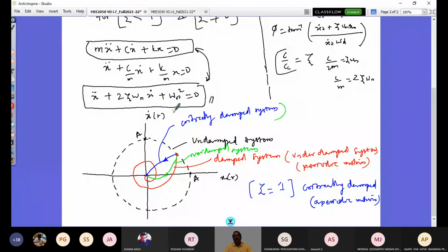When the gun is to be shot, you see that there is a recoiling mechanism. The recoiling mechanism should be such that it does not create any pressure on the shoulder of the army man. At the same time, it has to happen quickly. So for that, the damping present in the spring damper and recoiling mechanism would be critically damped, so that when it is fired, it won't be vibrating. The barrel will come back quickly to its mean position, and the next load of the gun can be fired. And there, if you have an over damped system, what will happen?